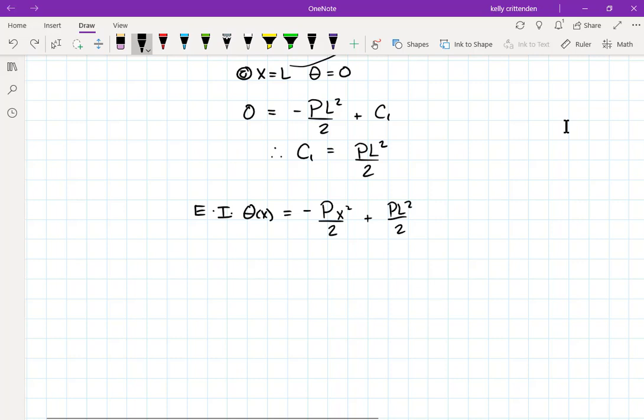So we could have that if we wanted it. And sometimes it's useful because one of your failure criteria is that the beam can't deflect a certain amount. That would be one of the things you would have to check. If it's not breaking or yielding, it might still deflect too much. So you might have to know the slope at these maximum points, or maybe the slope at any point. Our equation generates the slope at any point. The ones that are usually in the charts generate the slope that's maximum or at the end. But again, most of the time what you want is actually that deflection.